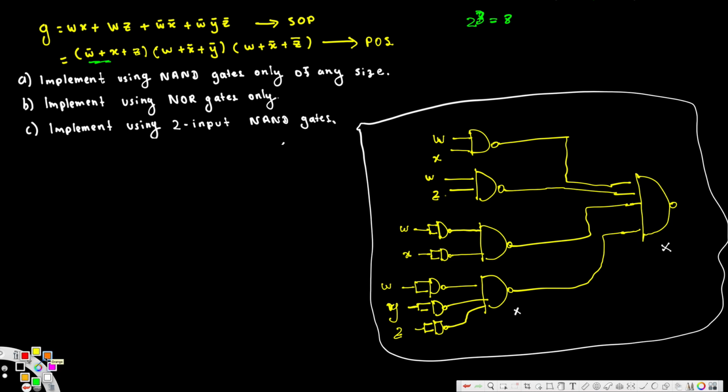Okay, so let's see what we can do. Here we have a 3-input circuit, let's say A, B, C, and that is a NAND gate, right? 3 inputs to the NAND gate. Now instead of writing it like this, we can also write this one with 3 inputs, A, B, C. Instead of this NOT, you can put a 2-input NAND gate with inputs tied together, as we saw before. This NOT means it's a NOT gate, similar to this one. So we can do that, right?